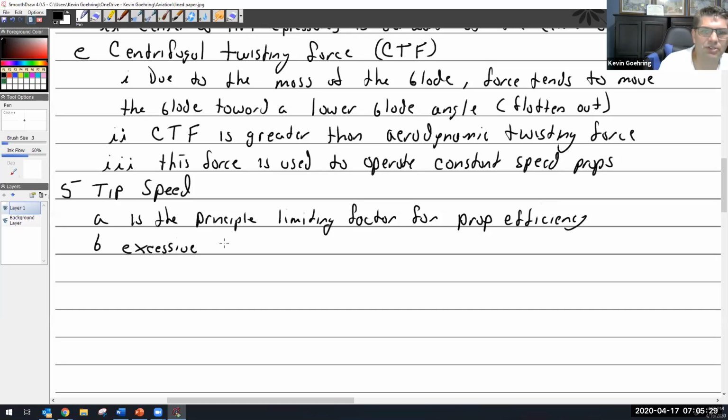So excessive speed causes flutter and vibration. Now this flutter thing is one of those things that I have a hard time wrapping my mind around. If you look at control surfaces on an airplane, even the ailerons and elevator on my little Cessna 150, they're balanced. They have to be taken off the aircraft and put on balancing blades, and there are lead weights in there because they have to get this perfect balance.